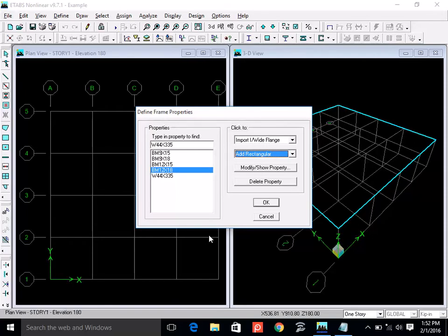But generally, 9 inches is too small to accommodate steel bars and to do the compaction. When you are casting a column, say a 12 feet high column, you have to insert the vibrator inside the column. So 9 inches is too small. Generally, people don't do that.